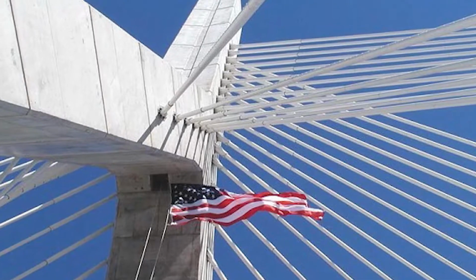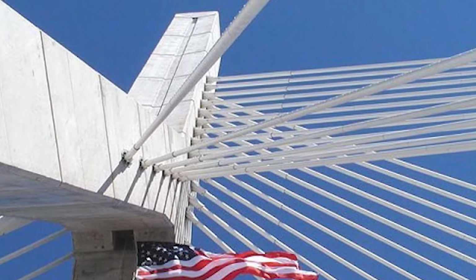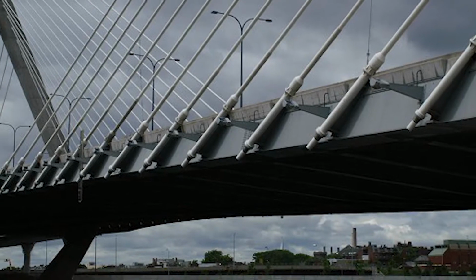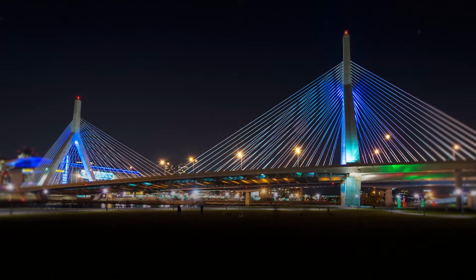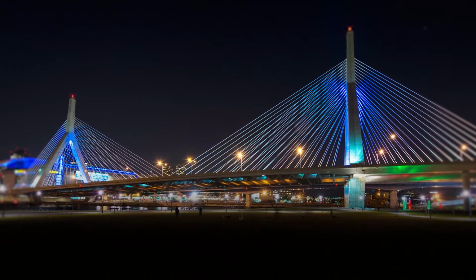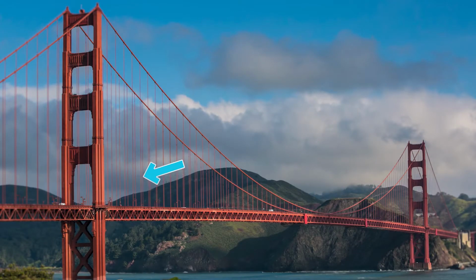The bridge consists of steel cables attached to both composite steel reinforced concrete pylon heads and main span, as well as the pre-stressed concrete side spans. Cable-stayed bridges differ from traditional suspension bridges in that all the cables run directly into the towers. Suspension bridges typically have secondary cables connecting the tower cables to the span surface perpendicular to the bridge.